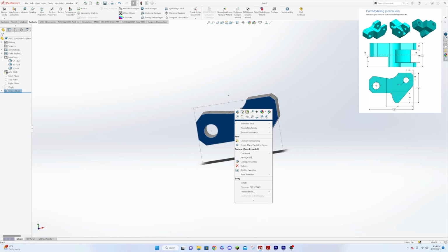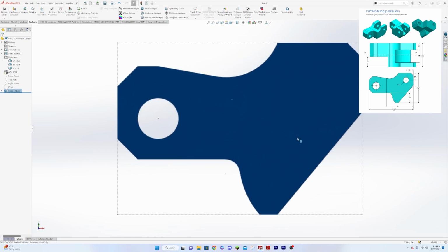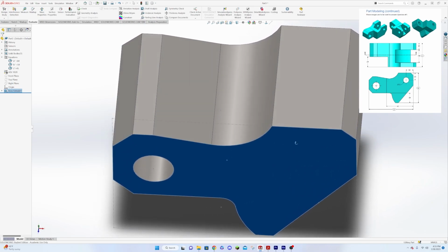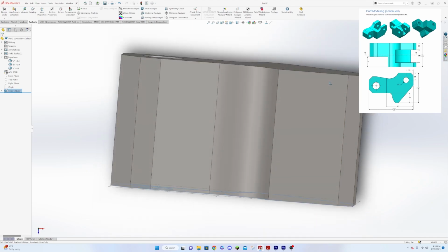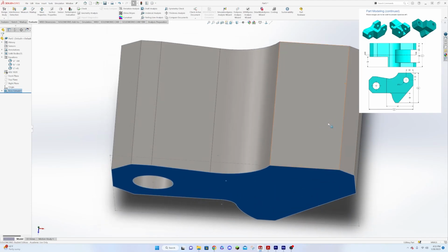All right, so if we look at this piece, we can see that when it's lined up here, if we look at the drawing, we're going to have a cutout here, and we're going to have an extruded cut here. And then if we flip it over just slightly, off this back face in 12 millimeters, we're going to have another cut in here. And since those are the dimensions that we're given, that it's related to the back face of this and not to the front face, then when we set this cut up, we're going to want it to set up so it's always 12 millimeters off that backside.